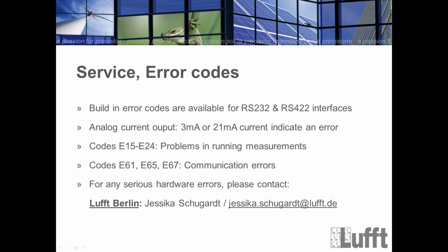There are these specially called communication errors, which we said E65 is mostly eliminated because it was a firmware thing that when the sensor was measuring and you tried to poll or ask for a measurement, then the answer was sometimes a measurement interrupted, and there was this E65 error for this purpose.